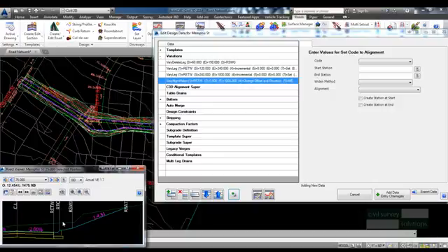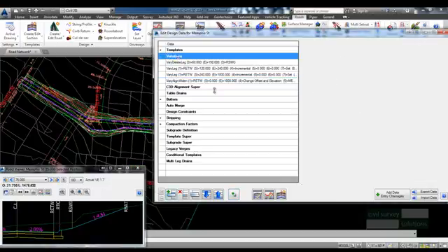In order to achieve this, the user could approach the task by creating more templates and applying them at relevant locations, or use the insert variation to create the top and toe of the retaining wall where required along the road. The insert section variation also includes the added functionality to specify tapering width and/or changing slope at the time of inserting the new codes.